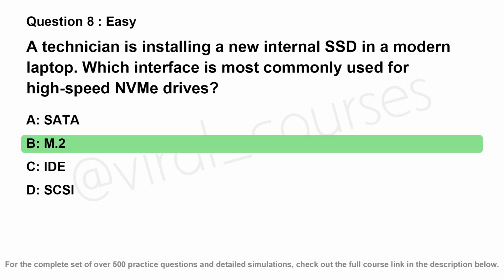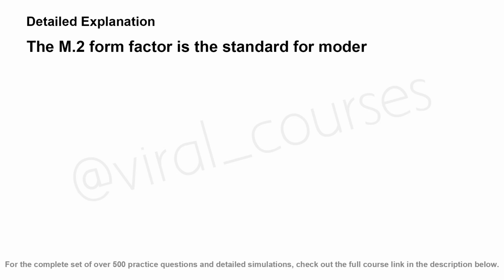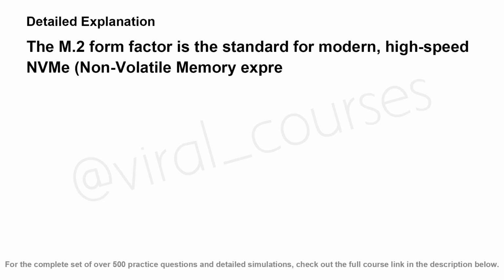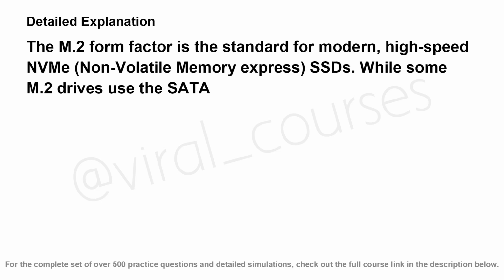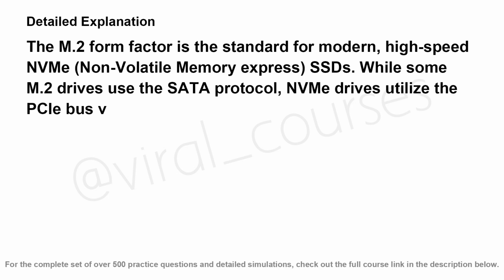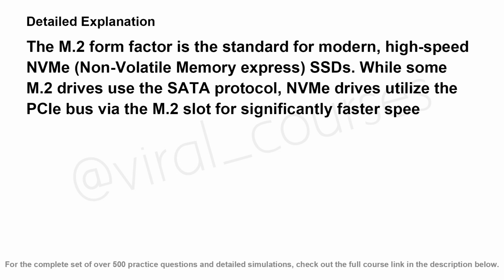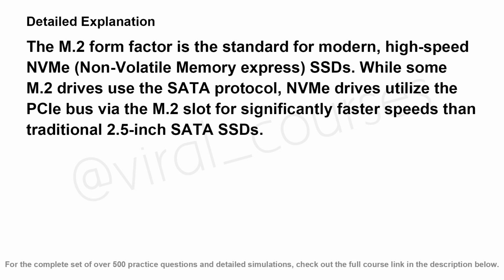The correct answer is B. The M.2 form factor is the standard for modern, high-speed NVMe (non-volatile memory express) SSDs. While some M.2 drives use the SATA protocol, NVMe drives utilize the PCIe bus via the M.2 slot for significantly faster speeds than traditional 2.5-inch SATA SSDs.